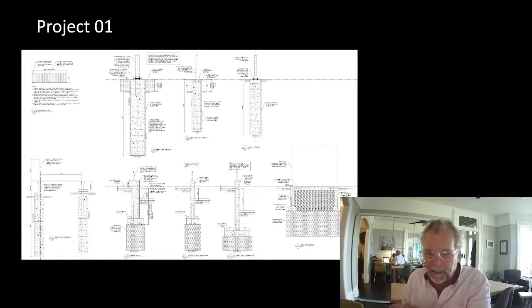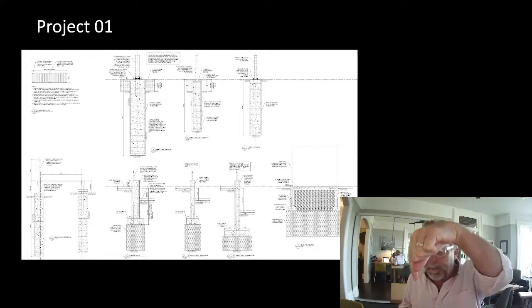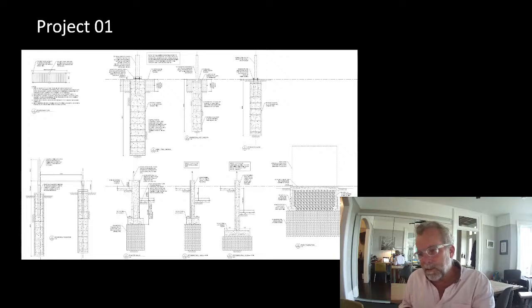So we backfill in with clear crushed stone. Water can't get in from below because it's a capillary break. It can't get in from above because there's a slab, and therefore, even though it freezes, it's not vulnerable to heave. Now, I just said something that I hope that you will call me on.